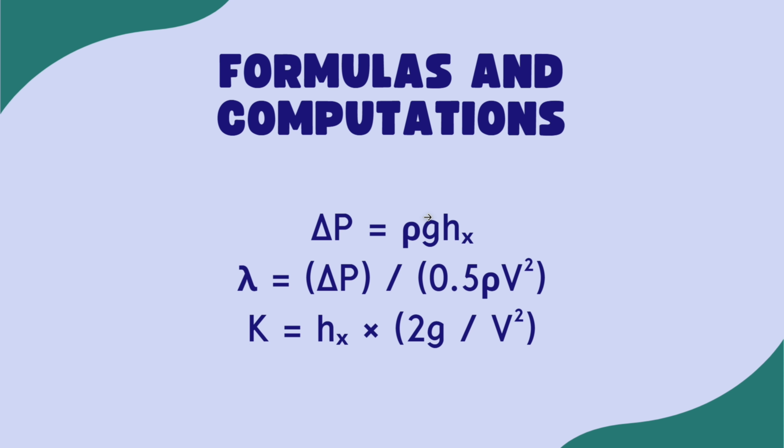To process our data, we used Bernoulli's and Darcy-Weisbach equations. We computed pressure difference, friction factor, and the loss coefficient using these formulas. By substituting our measured head losses and flow velocities, we derived all the lambda and K values you saw earlier.